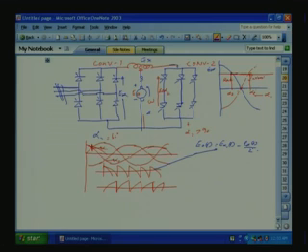Now, we know Er is equal to E alpha 1 t minus E alpha 2 t, because of the center tap. This includes the DC as well as the ripple part. So, DC will cancel, only the ripple will come across this one, because both have the same DC. So, the inductor will only support the ripple value.